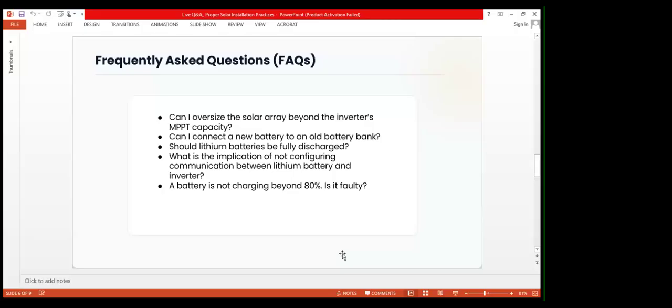You know that I can't increase the charge current beyond maybe 25 amps, so that the 5 will be the one for the old batteries, while the 20 amps will be for the new battery, because the old battery definitely will be taking some current, but you should not take it high because the new battery will take the highest current. So that's that. If it's in series, it's even not advisable.